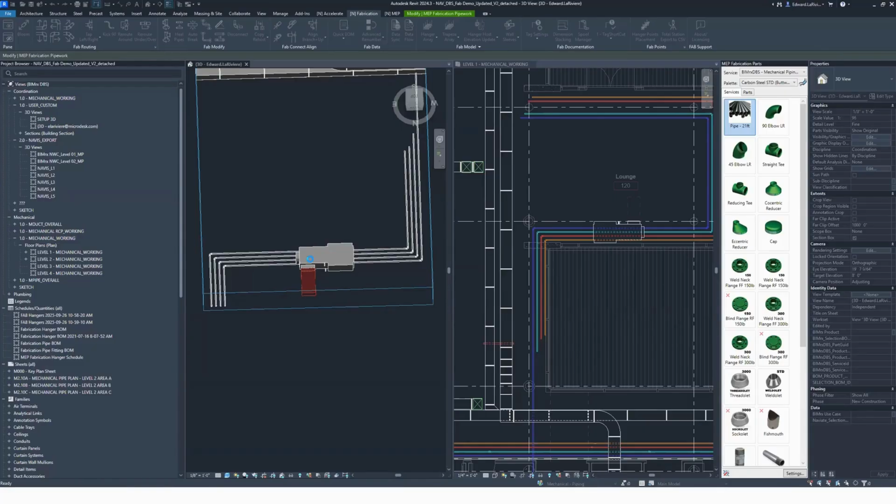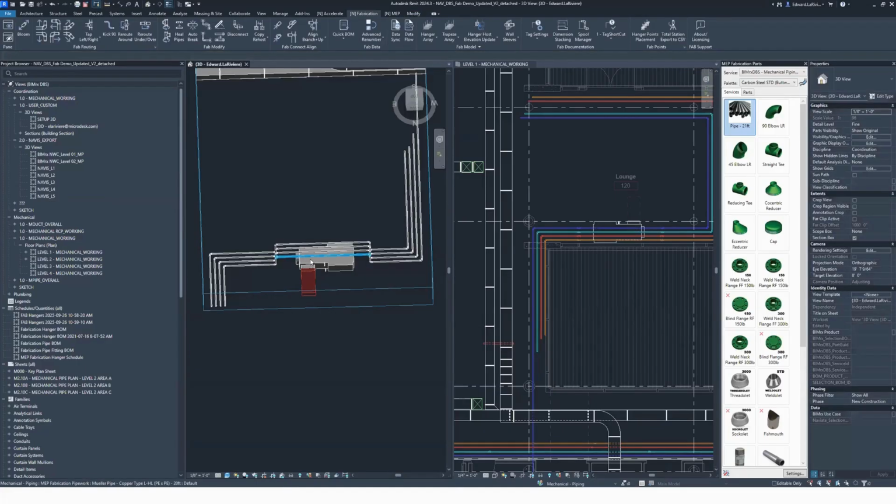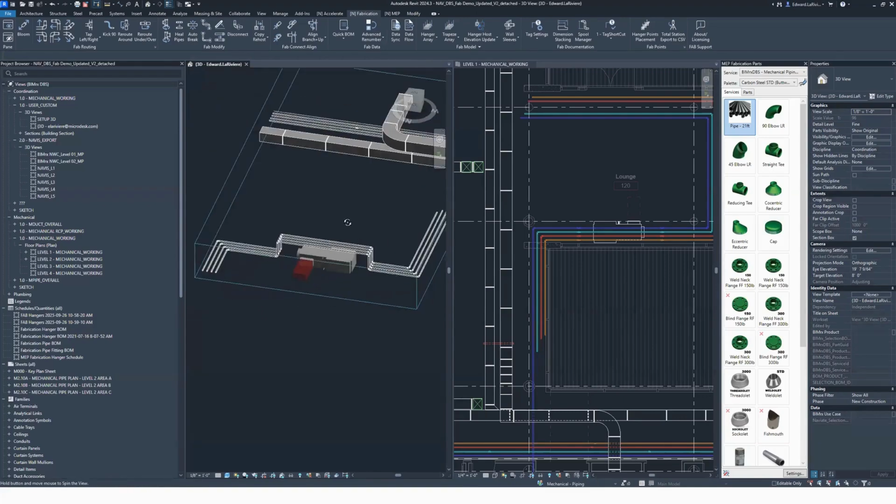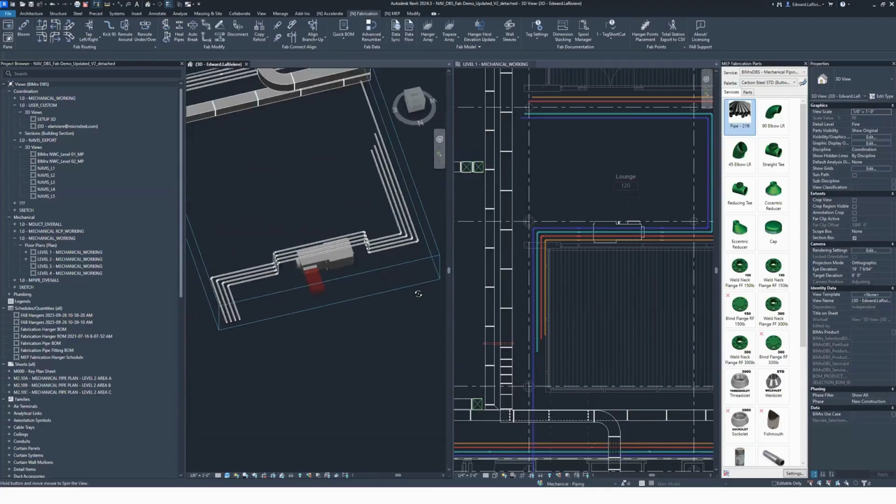I'm just clicking 2 locations on that pipe that I want it to leverage. I never actually told it to interact with that element. I just said on this side of the pipe, on that side of the pipe, offset and angle. So you could have your other elements linked in and just show them through a link. You could have your other elements just be a measurement that you made in the field. You might not even have it modeled. And you just know in this area, you got to jog around something. Whatever it is, get those values in there, clear your clash, and you're good to go.